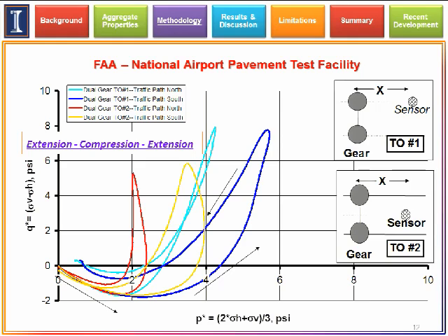When you have this type of fast moving load, your granular materials often experience directional dependency, and this directional dependency cannot be well portrayed with the conventional AASHTO T307, where you pulse your specimen only in the vertical direction, but you also have horizontal stiffening, material stiffening in the horizontal direction.